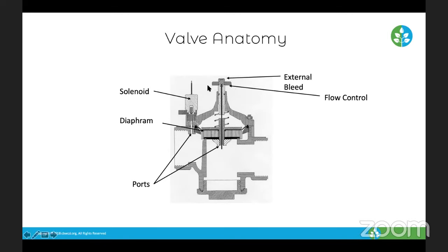And again, that's the control valve, the cross on the top. Again, the bonnet is the upper portion of the valve. Then the seat: at the bottom of the diaphragm, there's a rubber seat, which sits along the body of the valve itself. That's what keeps the water from seeping through.